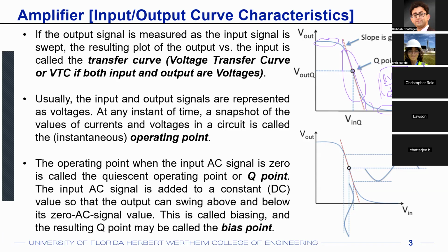Of course, the voltage gain in this case is negative. Why is it negative? Because again, the output reduces as your input increases. So there's an opposite relation between your input and output, a 180-degree phase difference between your input and output. And that's why the actual value of gain is negative in this case, but the absolute value is what we are interested in at this point.